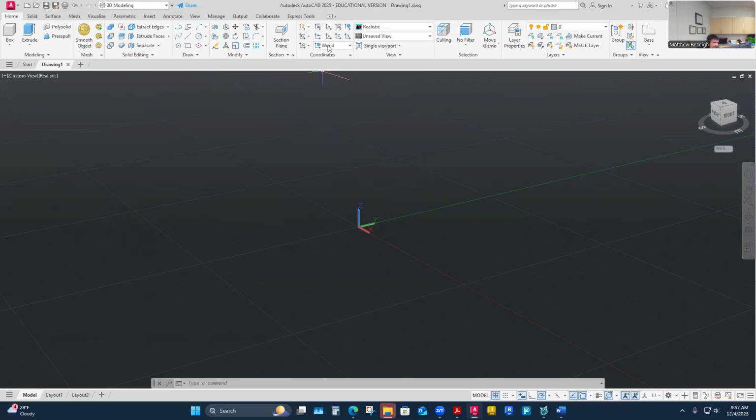And then we can move our coordinates around. We have this new little drop down menu that will move our grid to these planes. Right now, I guess it's on the world, which is just where I'm looking at right now. If I go to top, I don't think it changes much. Top is kind of like the world, but the grid stays on either top or bottom. Top and bottom almost look the same, but you can see that the UCS Z is now going down. It's like I'm on the bottom, and Z in the positive direction is down and away from me because I'm viewing this from a bottom grid plane. If I go back to the top, you can see the UCS turns and Z is now positive. So I'm moving around the UCS when I change this drop down.